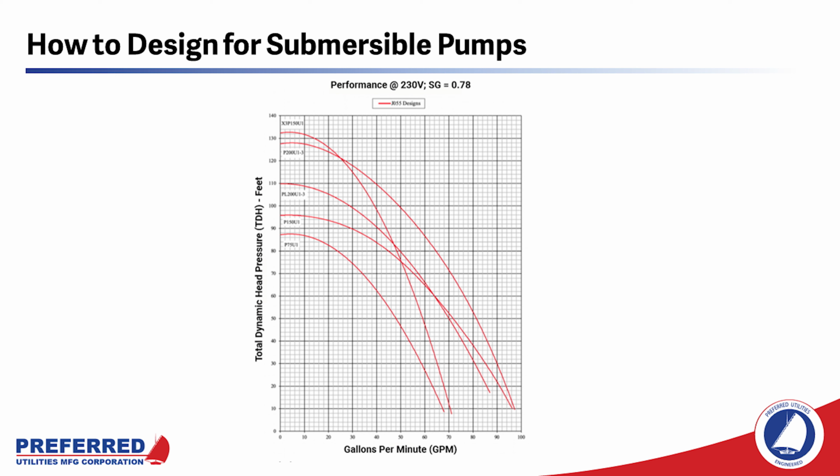So if the only place they'll let you put the positive displacement pumps is 300 feet away from the main tanks, it's unlikely you're going to be able to pull oil 300 feet reliably. So that's a situation where submersible pumps might work better, so you can push the oil through the whole system. So you would start with this pump curve, and I don't remember if this is Red Jacket or FE Petro. Someone else might recognize the part numbers.